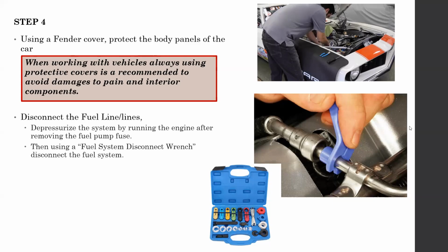But electronic fuel injection systems have a small issue because their fuel system is pressurized, right? As soon as you crank the engine, the system starts to pressurize. Unless you have not started the vehicle for some time, the fuel system still has pressure. In such a case, you need to depressurize the fuel system.